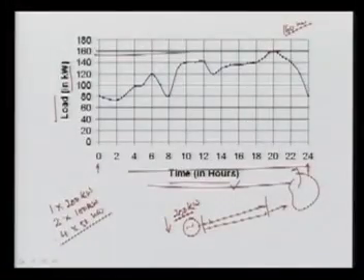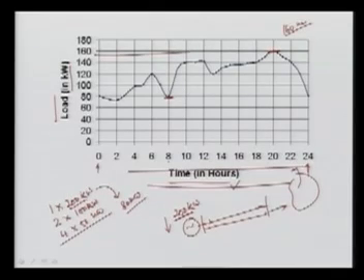Take the example that at certain durations the load is less, equal to half of capacity. At 8 a.m. in the morning, the load is only 80. What will happen? You are running one unit continuously for all 24 hours. At one time it is maximum loaded, and the remaining time it is half loaded or partially loaded. If any generator is partially loaded, the efficiency will not be good, because efficiency is highest when it is loaded to its full capacity. So the efficiency will be less, and the cost of electricity generation will be more.